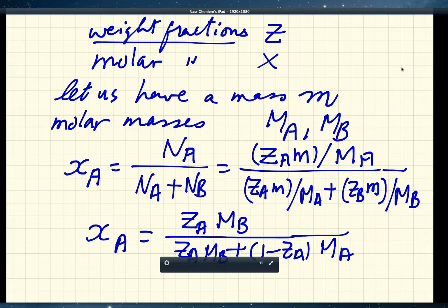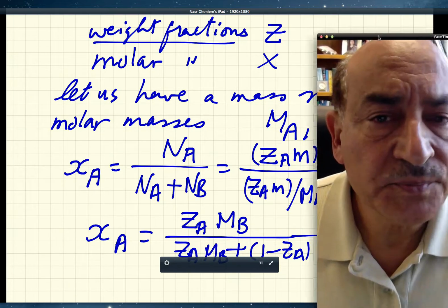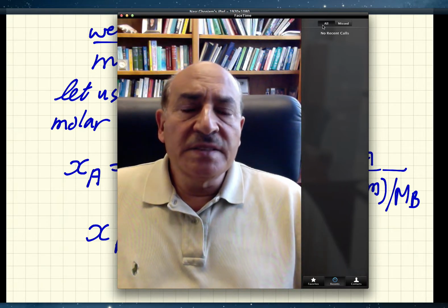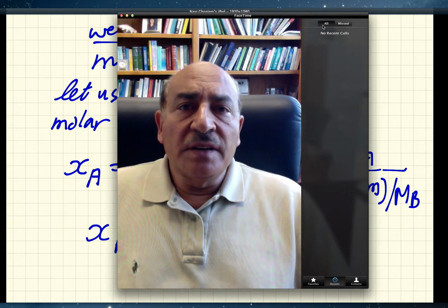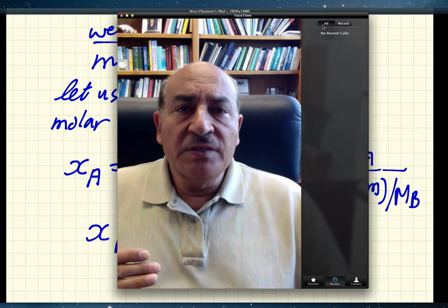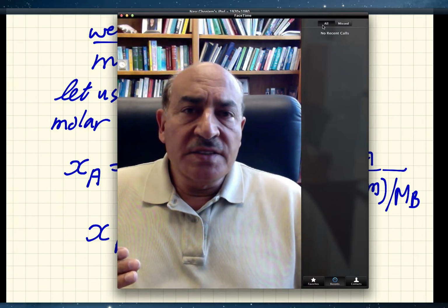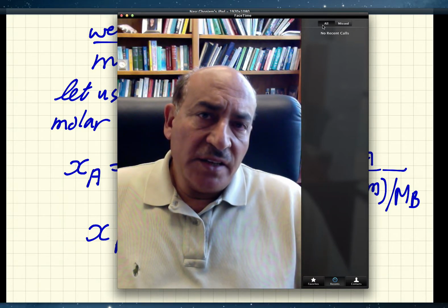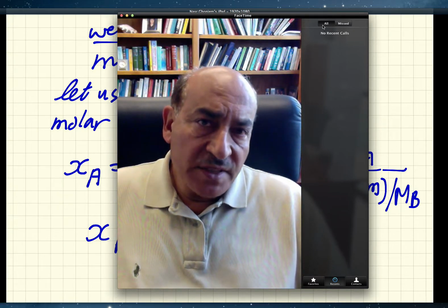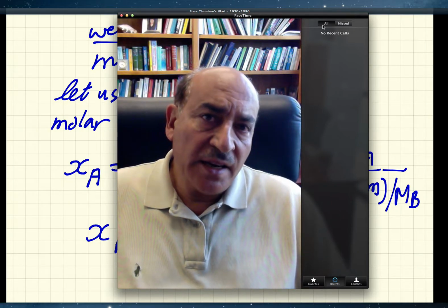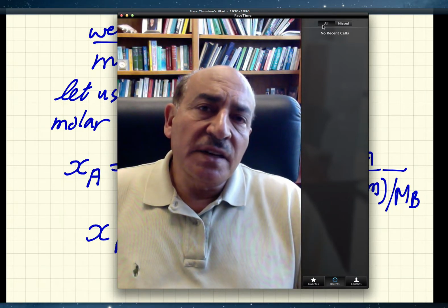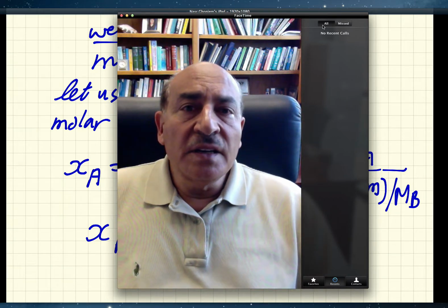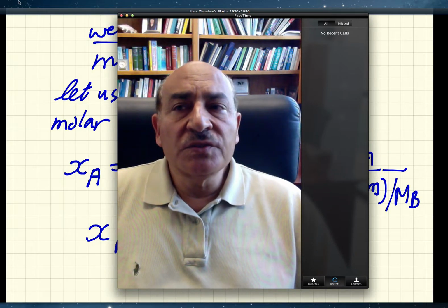And this equation can relate the weight fractions to the molar fractions that we can use right away. So with this part we have a complete determination: we can convert the weight fractions that we get from the phase diagrams to the corresponding molar fractions that we use in our equations for the moments on the tie line, and therefore we can get the corresponding concentrations for any given temperature. And with that, I think we're going to stop the lecture.